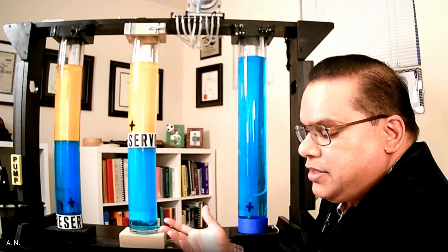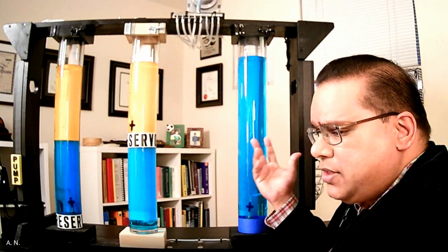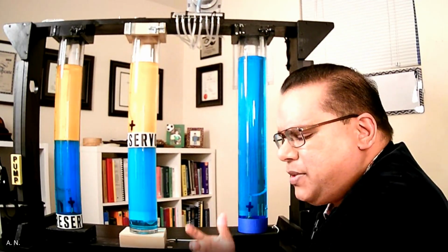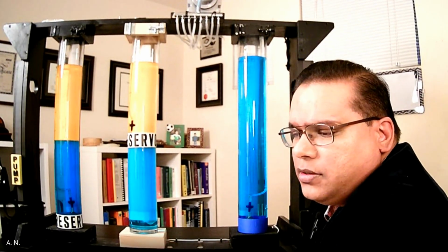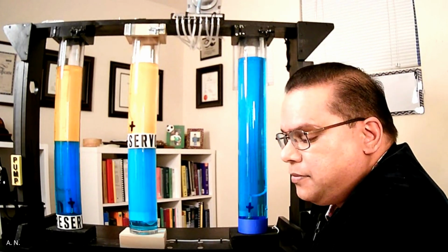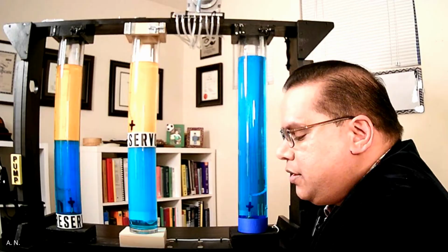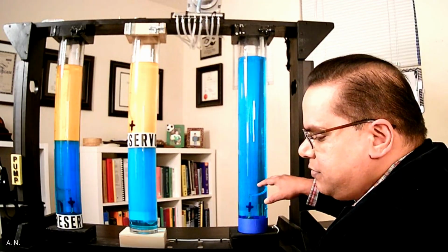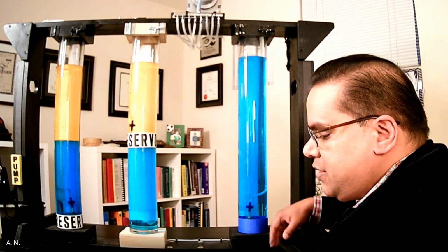So we know that that's not true, and you can do things like this too. And you can also disprove the rules of thumb, like 10 feet per second for annular flow. That's not true at all. It's actually 10 meters per second. So the thing to notice here is that we're generating these bubbles, and we can control the bubble size and so on, right?